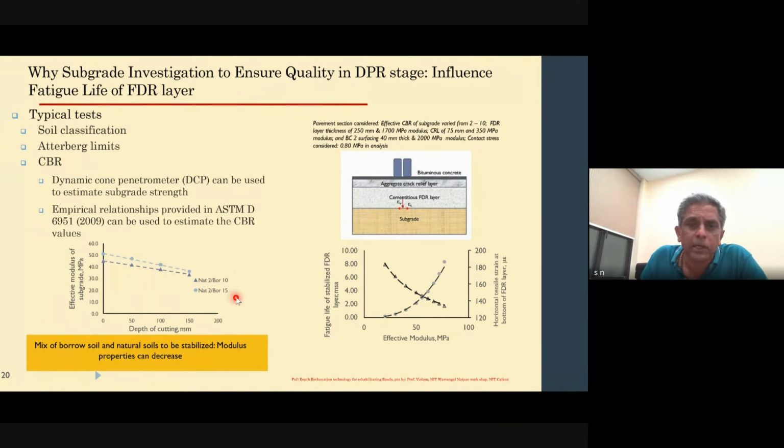about 0.25 meters deep. Now, estimating the spread of the cement. You have 113 kilograms of cement, which needs to be spread across 5.65 meter width and 1 meter length. So making appropriate calculations, you can get that the rate of spread of cement should be around 20 kilograms per square meter of that roadway. If I take 20 kilograms of cement and spread it per square meter, then I would end up getting a mix which has about 4% in terms of weight percentage.